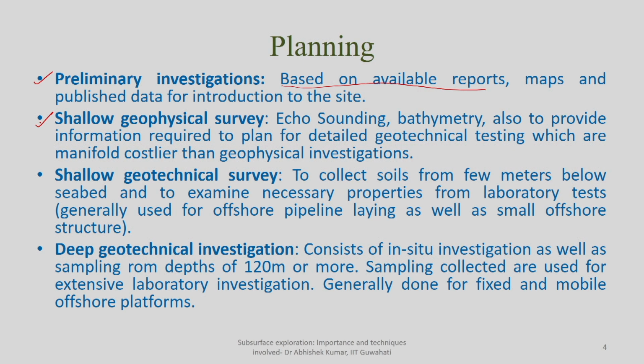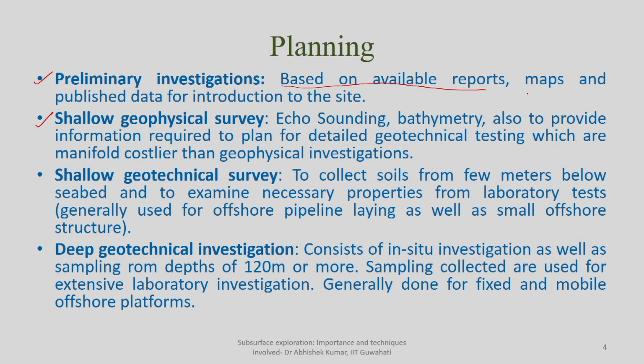If you find your site is suitable for detailed investigation, whether geophysical or geotechnical, based on reports, maps and published data, then go ahead. A lot of times, because of environmental, ecological, seismic, geological or meteorological issues, people do a lot of surveys offshore even for construction of important structures, particularly nuclear power plants.